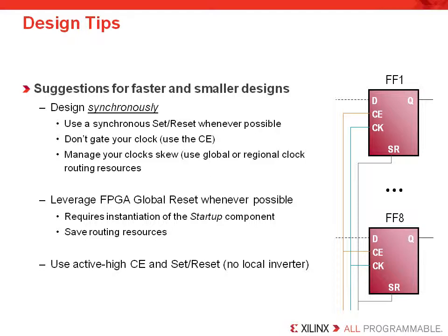And don't forget to keep your control signals active high, so you don't need a local inverter to be mapped to each control signal input. These are not dedicated in the silicon, and that would force the synthesis tool to waste a LUT input.